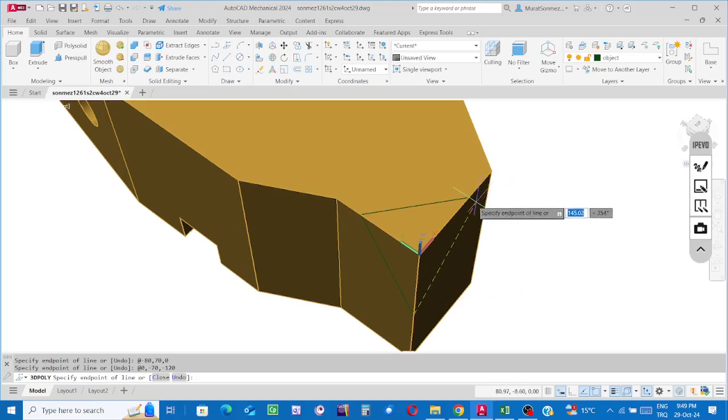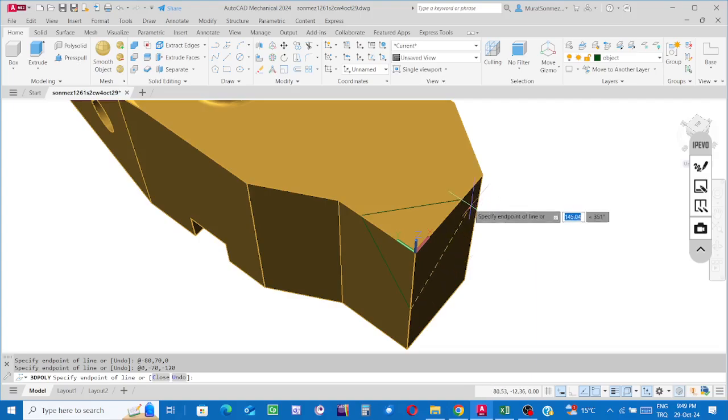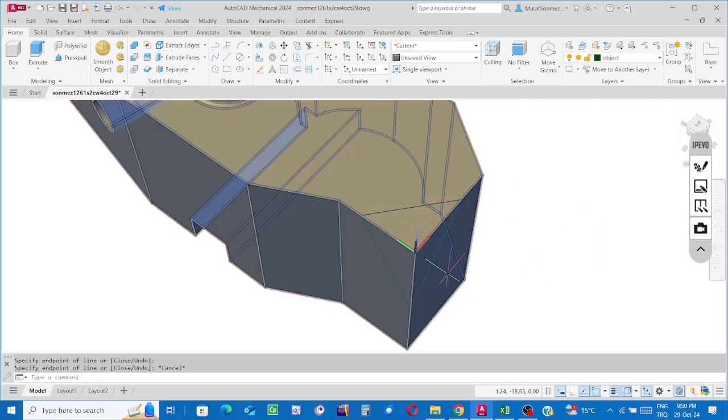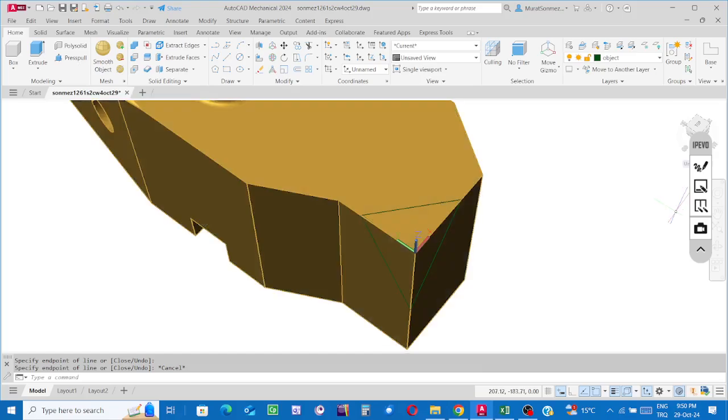And then the third boundary line, I'm going to use the snap technique. Indicate the starting point, the first point, as the ending point of the third joining line. No need to write any coordinate value. Press the escape button. Here is the sketch. Okay. And then the rest, apply the extrusion process.